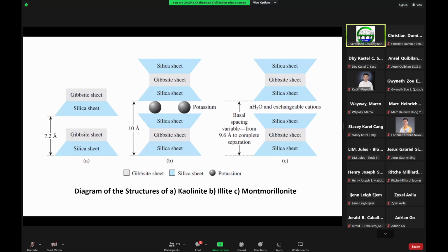So what this figure is telling us is that when we talk of clay soils, they have a different soil structure than the other soil types because they are mainly composed of sheets, and that gives them a different behavior. For example, in terms of permeability, the flow of water in clays is very slow.